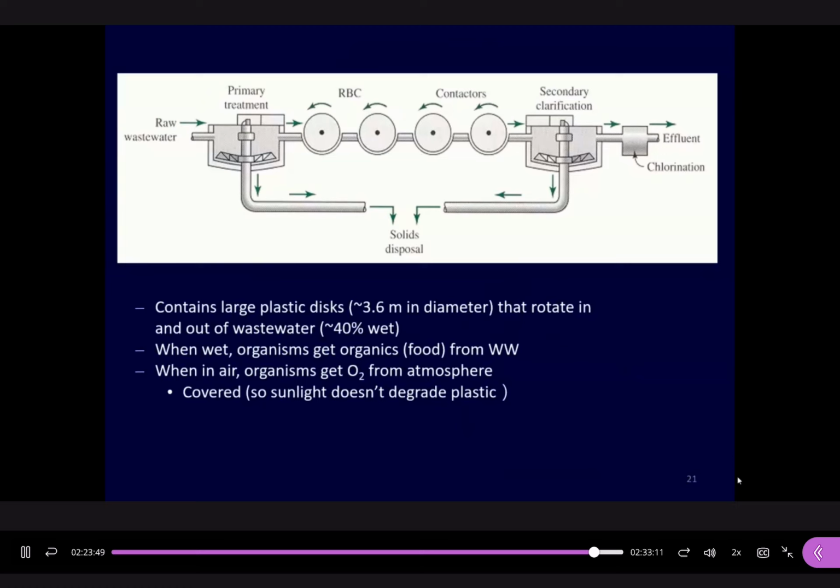So far for our biological wastewater treatment, we have been focusing on aerobic treatment, right? Aerobic treatment means oxygen serving as electron acceptors. So you see, every step we need oxygen. For the trickling filter, you see there's spray of wastewater. During the spray, the water droplets get in contact with air, so the droplets pick up certain oxygen.